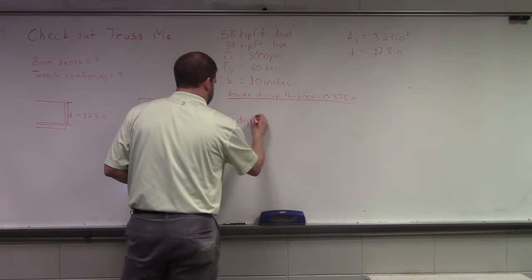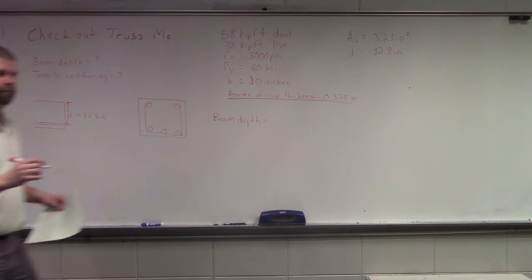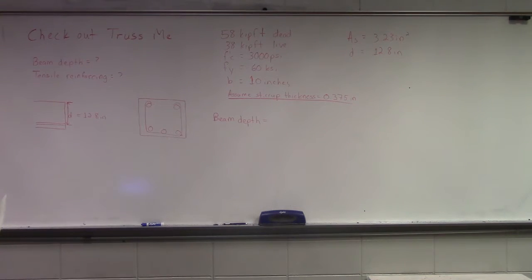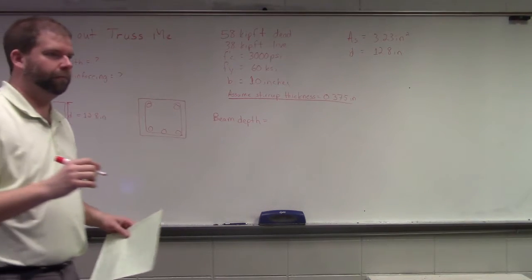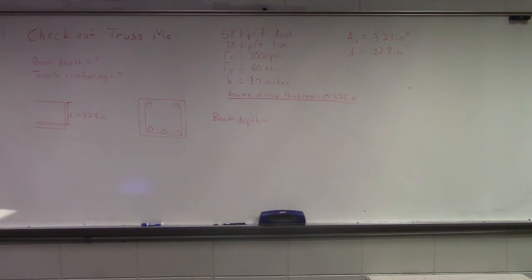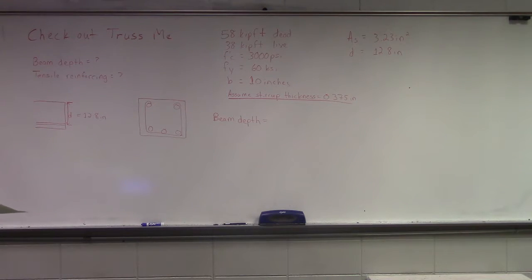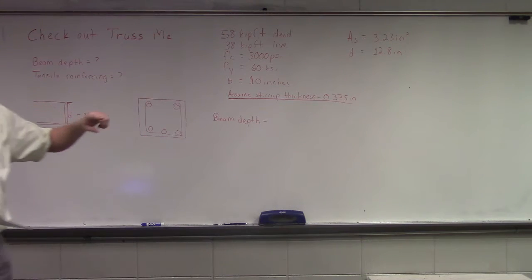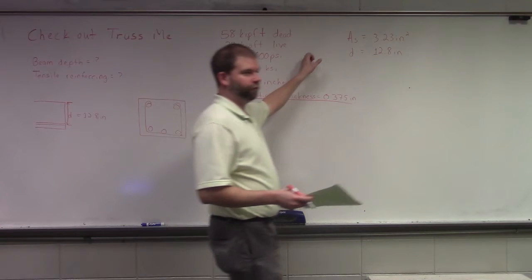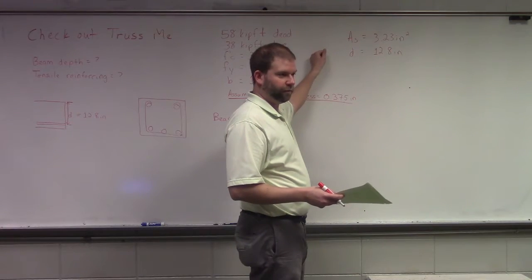I have a quick question. Yep. In this example, where we got 12.8, is it like a slab? This is a beam. Why do you only have the one reinforcing steel, and not one towards the top? This would likely have reinforcing steel at the top, yeah. The steel that we're determining is steel for the tensile face.